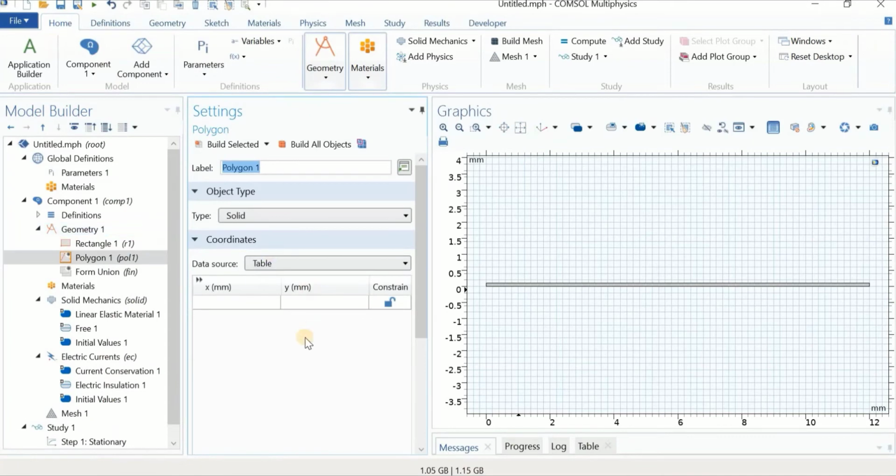In fact, when you use the polygon, you add the points to make the polygon. Because here we have a triangle, which is basically the 2D view of a micro pyramid, we are going to use 3 points. Based on the geometry that I know, I'm going to enter the coordinates of the 3 points of the triangle, and then I will explain these numbers after I create the triangle.